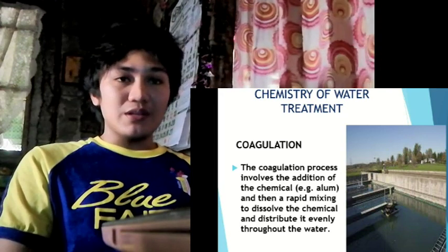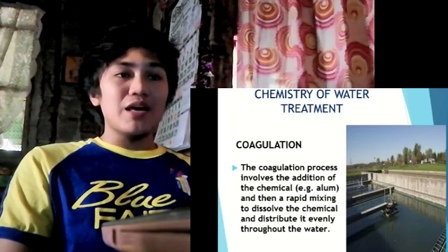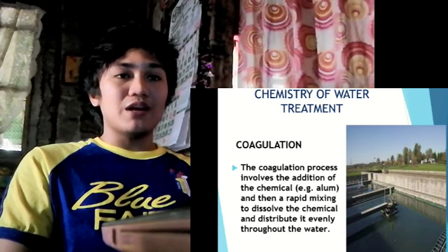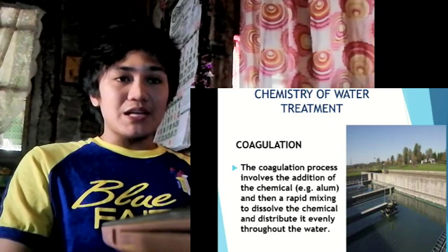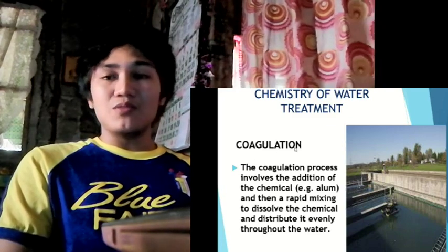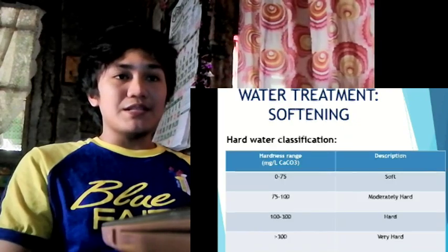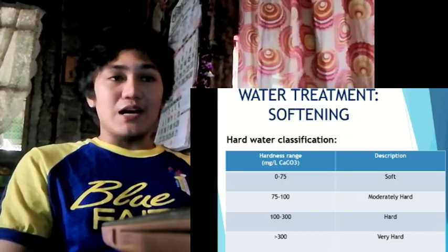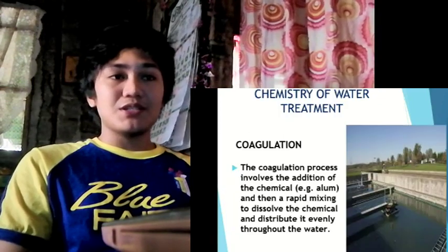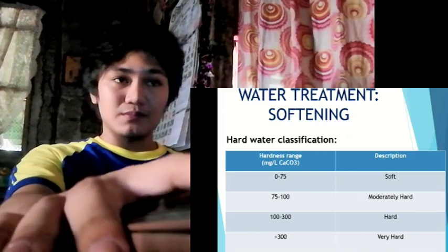The coagulant that is added must precipitate out of solution so that high concentrations of the ion are not left in the water. Such precipitation greatly assists the colloid removal process. Coagulant aids. The four basic types of coagulant aids are the pH adjusters, activated silica, clay, and polymers.